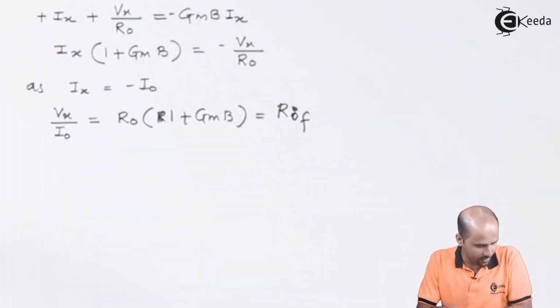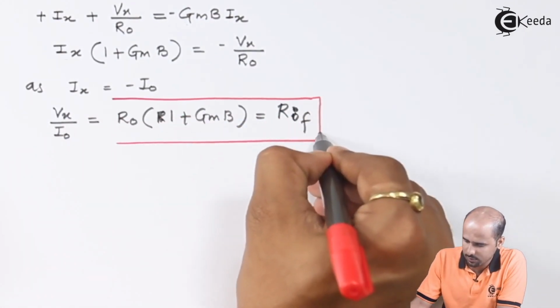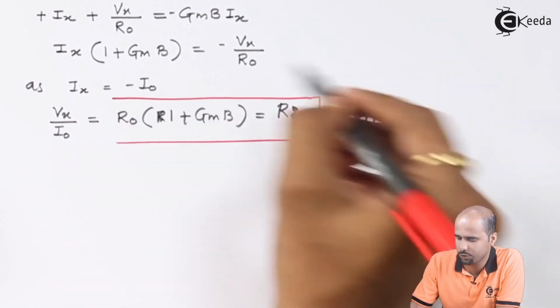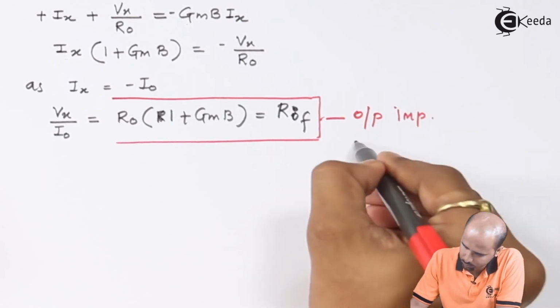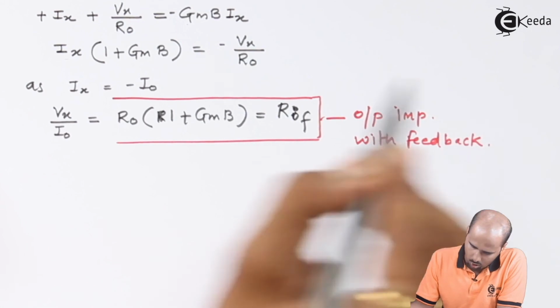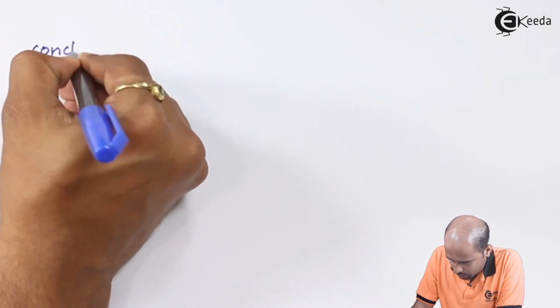Yes. So the final value we have got is that the output resistance with feedback is nothing but an increased value compared to the output resistance without feedback. As far as all the three values are considered, we got that the gain factor is reduced, input resistance increases, output resistance as well increases, right? So we'll form a conclusion part.